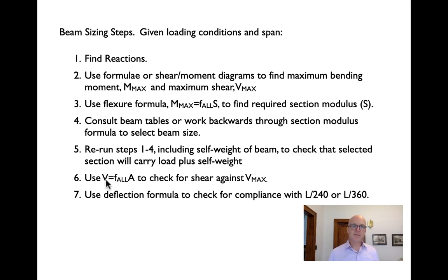We'll use maximum shear equals allowable stress in shear times cross-sectional area to check that we're not exceeding the maximum capacity of the beam in shear. This is a rare thing except for short beams and heavily loaded ones.